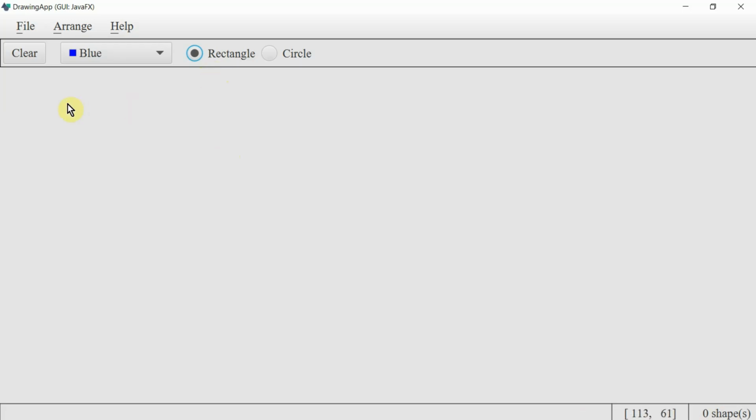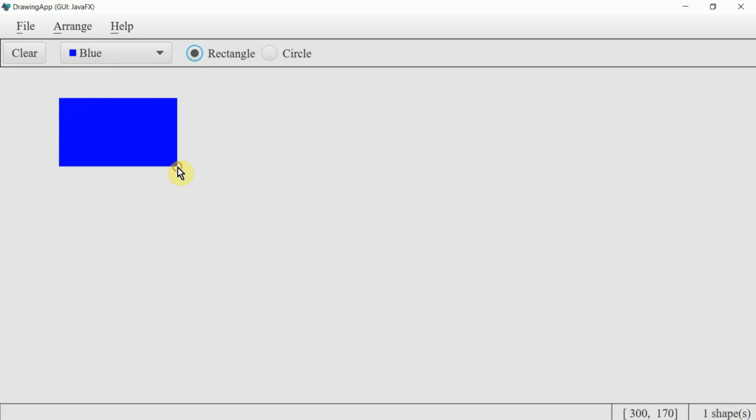So in order to draw a rectangle, very easy, I select a starting point where I want the rectangle to be located, then I click the mouse and that point will form the starting point of the rectangle, so the top left point. When I hover over it, we see the properties down below in the status bar. The starting point has a coordinate x and y with values of x 100 starting from the left and y 53 starting from the top of this plane. Now the toolbar doesn't form part of the plane. The height, the h, is 117 pixels and the width is 200 pixels, the w.